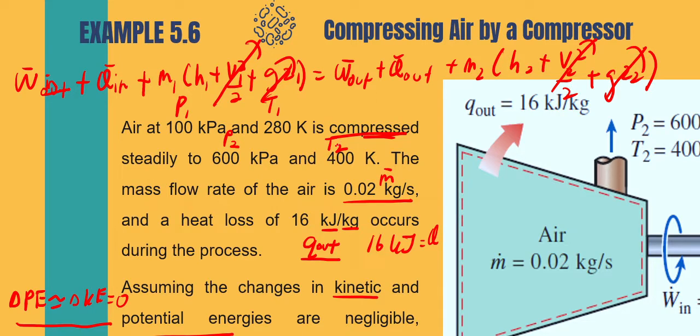And then we know that for a compressor, is it work in or work out? It requires work, even though it is not given in the question. So for a compressor to operate, we require work in, but there is no work out, so you remove work out. And given that there is Q out, obviously no Q in, so you remove Q in here.